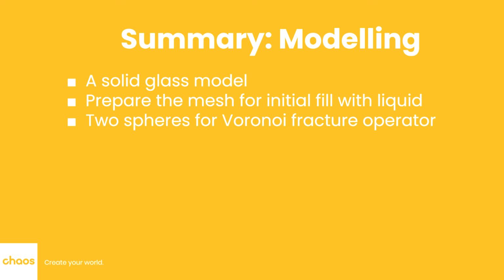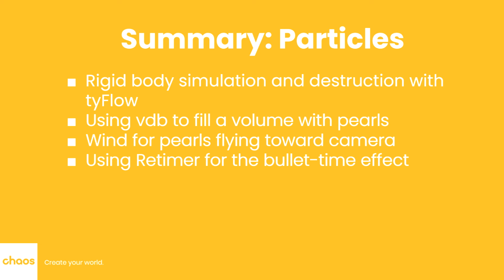In this tutorial, I demonstrated creating a milk tea shattering effect with tyFlow and Phoenix, using a solid glass model and 2 spheres for improved glass cup fracturing. tyFlow handled the rigid body simulation and destruction. VDB filled the cup with pearls, and a wind force made them fly towards the camera. The intuitive retimer option in tyFlow achieved the bullet time effect.